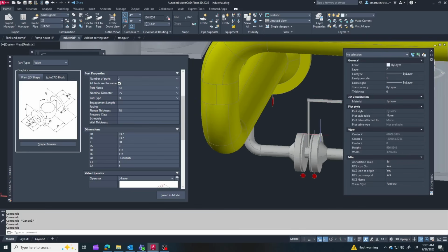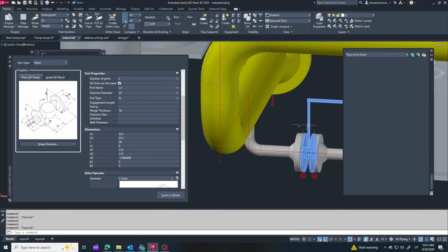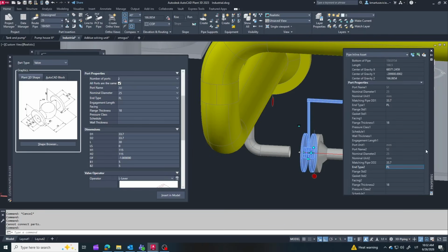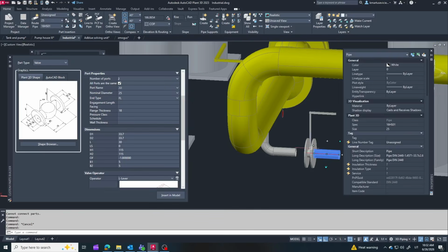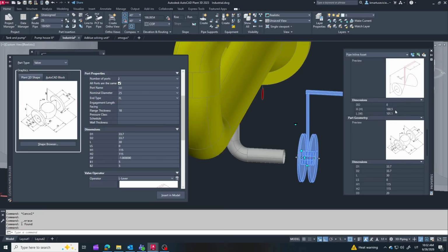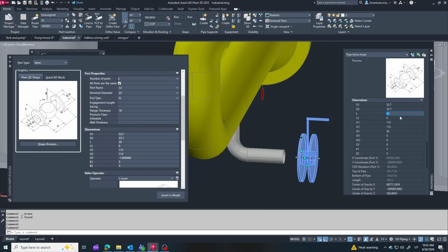Here I decided that flange connections would be unnecessary for the small drain valve, so I changed it to plain ends to keep the model simple. In a real project, however, small drain valves are often supplied with threaded connections, so always choose the end connection according to your project specification and the valve manufacturer's design.